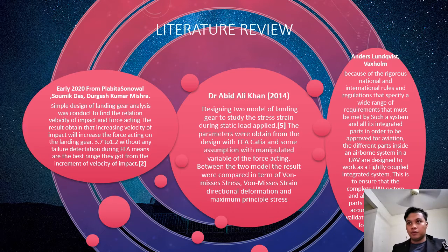For the literature review, early 2020, from Pallavi Sonowal and Somi Das, Dargesh Kumar Mishra: a simple design of landing gear analysis was conducted to find the relation between velocity of impact and force acting. The result obtained is that increasing velocity of impact will increase the force acting on the landing gear. They got data of 3.7 to 2.1 factor of safety without any failure detected during FAA. It means that is the best range they got from the increment of velocity of impact.